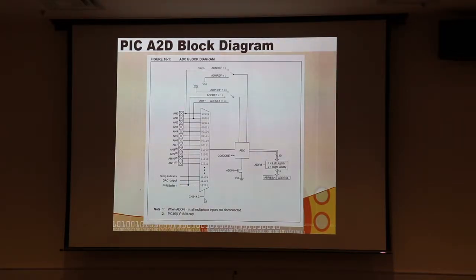It does have these 5 bits of digital input to determine which channel is selected. So it's actually a mixed signal device. It's got digital signals and analog signals both. But the signals coming in here are all analog voltages, and you're getting an analog voltage out, and it's selected digitally. Okay? So that's your analog multiplexer.